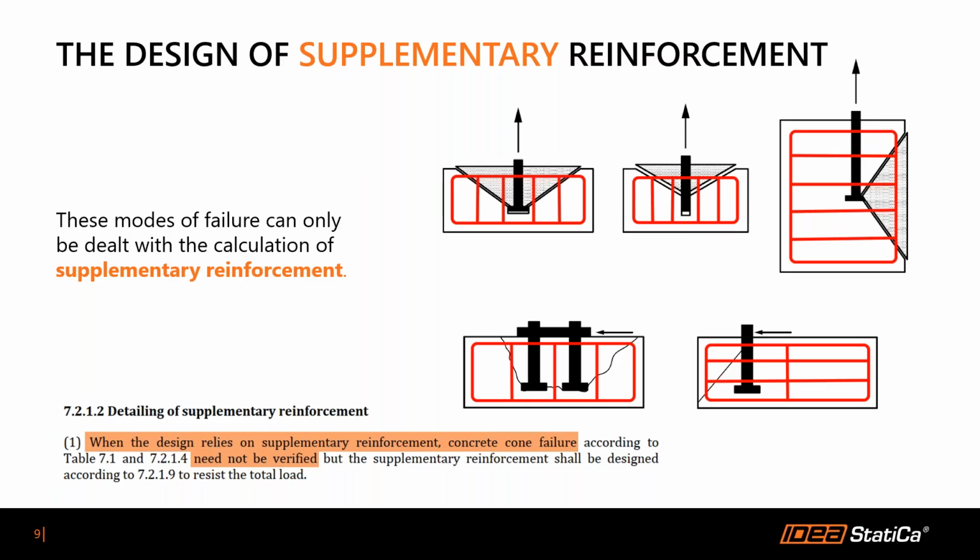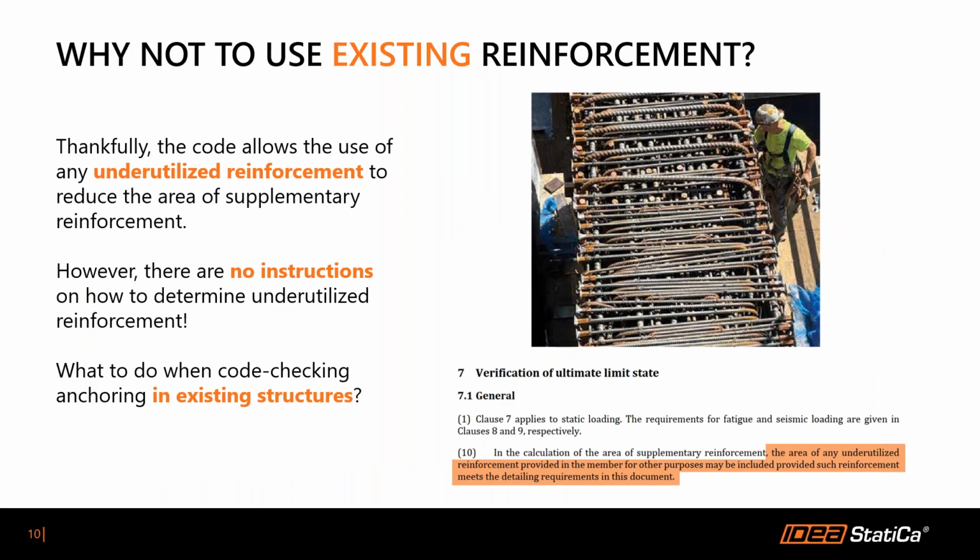That's fine, that's very good, but it also says that you have to design this supplementary reinforcement on the forces that arise from the anchoring that are transmitted through anchors to the concrete. So now there's a second problem that you have to somehow calculate these forces and take them into account when designing the supplementary reinforcement.